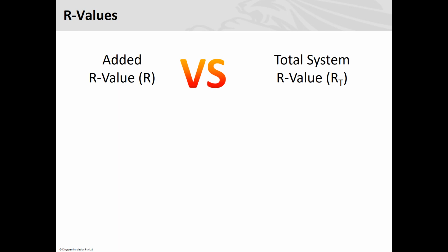Yeah, excellent. So we've got both climate zone 4 and 5 and climate zone 6, where, depending on the reflective surface of your roof, how much heat would be drawn in there, there are reflectance values given in the NCC, 4.1 to 5.1. So 5.1 is for your darker roofs, your blacks, things like that. And then in climate zone 6, 4.6 and 5.1 for those. And then typically R2.8 for your walls.